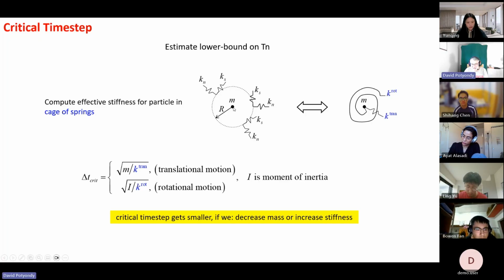We're going to go to every particle, figure out what these are, compute these 2 terms, and say that particle is vibrating this fast, so it needs a time step of 1e-3. But there might be one here that's vibrating even faster. So we go through all of them, and we take the smallest of all. And that's how we get the critical time step. Okay.